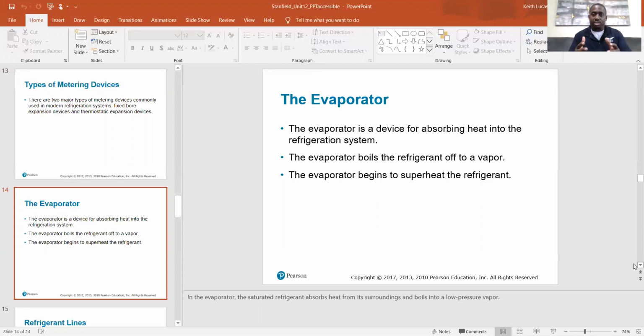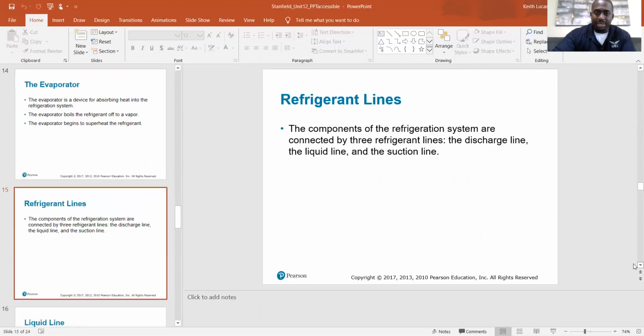So when that heat comes across it, it's going to absorb the heat from the refrigerant and blow it out at the top. Again, I tend to get ahead of myself. I hope it's making sense though. But the evaporator is where we absorb heat. The condenser is where we reject heat. Those are your two coils, and those are two out of your four components in your refrigeration system. And like I said, there's more components, but they're not critical to make a basic refrigeration system.